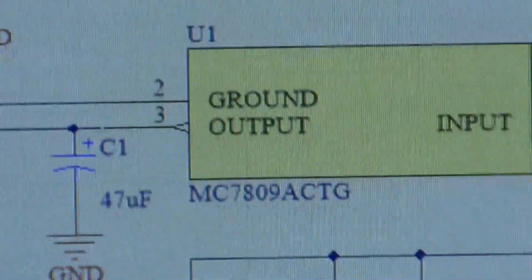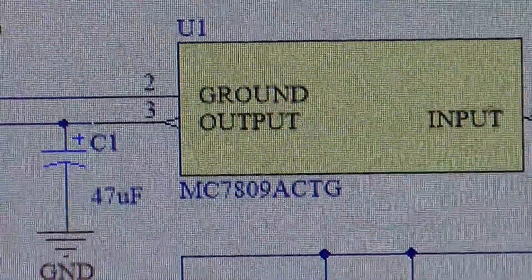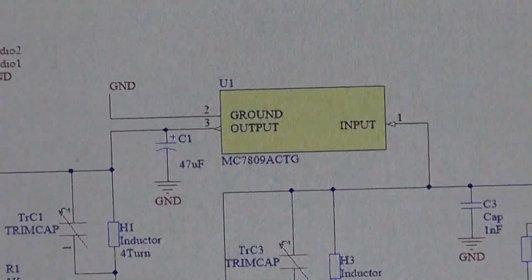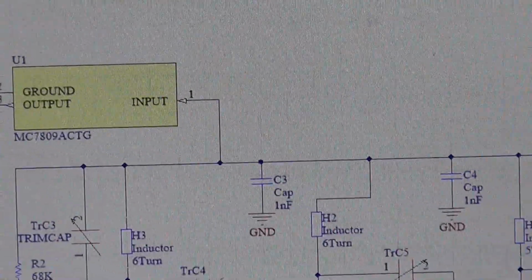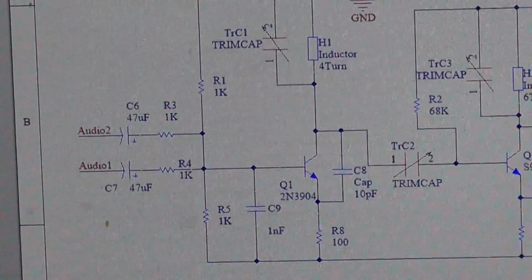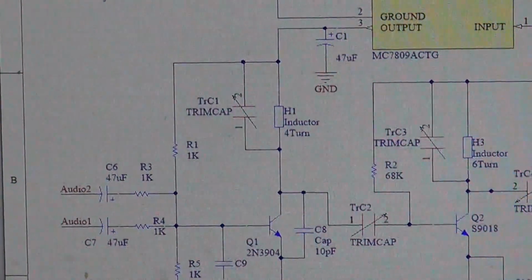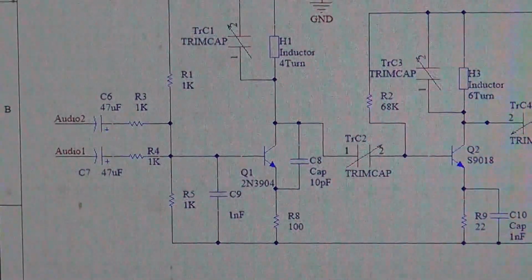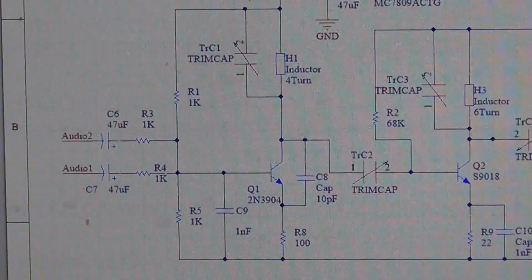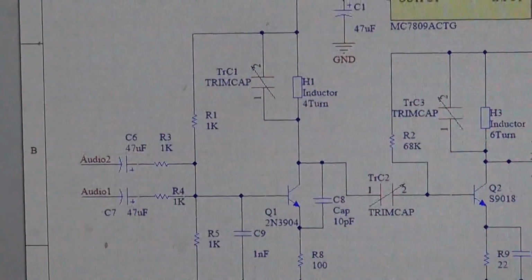Actually, I did not use that integrated circuit, which is simply a linear regulator to reduce the input voltage of 12 volts or higher to 9 volts. Right now the oscillator is receiving 12 volts, and like I explained before, for the FM modulation, the transistor's internal capacitance will change based on the applied voltage.